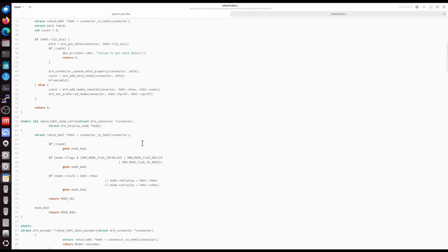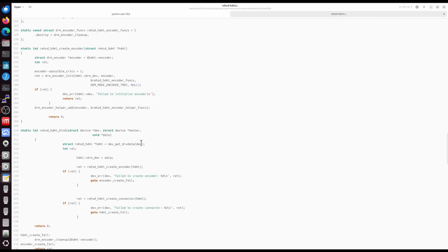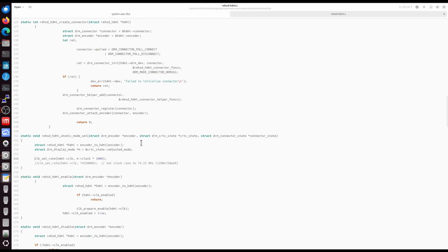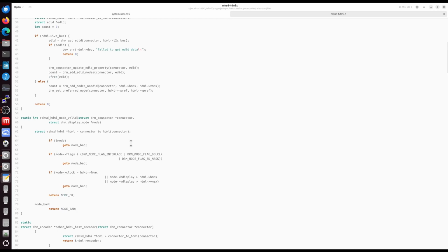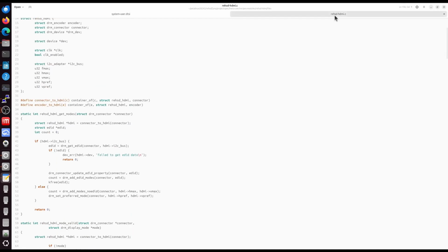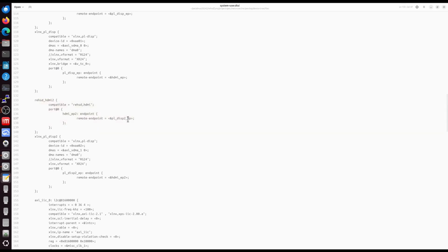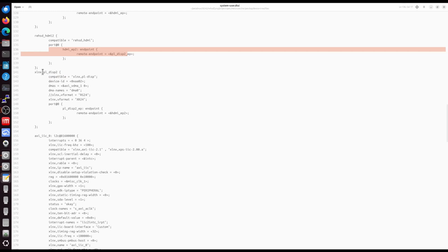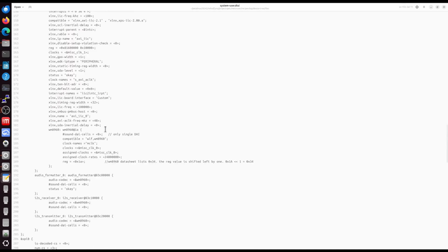What I did is I looked at the Digilent one and basically modified that. I stripped it down because I'm not using a timing controller, and I don't support flipping resolutions on the fly. I'm really just saying I'm going to support 720p output and call it good. So I put that in there. I said I'm going to use an HDMI as an endpoint on this. I am leveraging the programmable logic Zynq driver that I have included here, very much like my primary HDMI output.